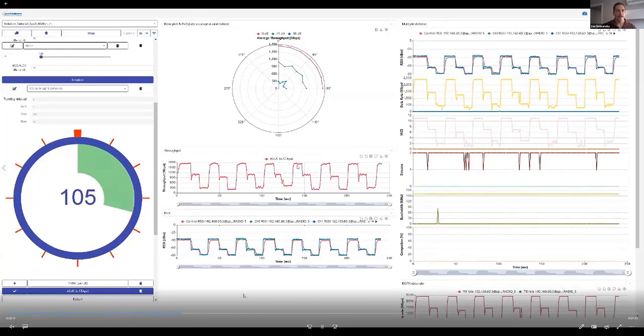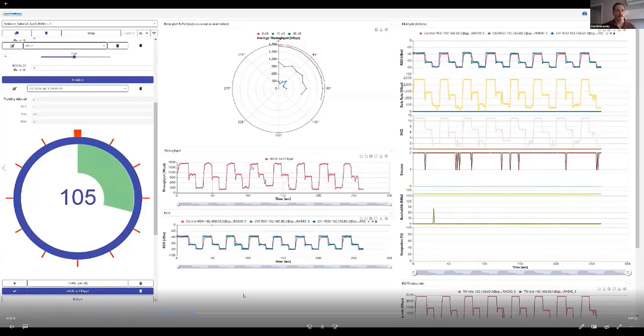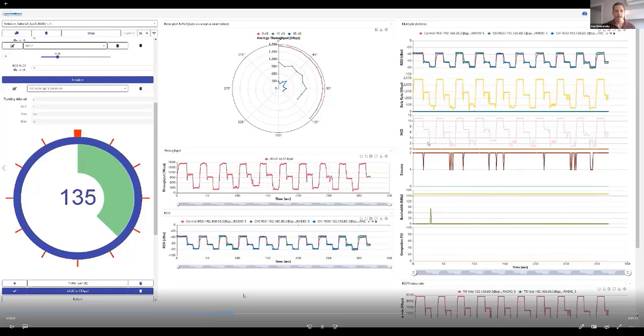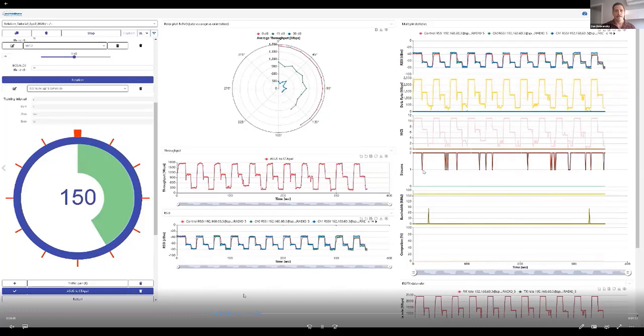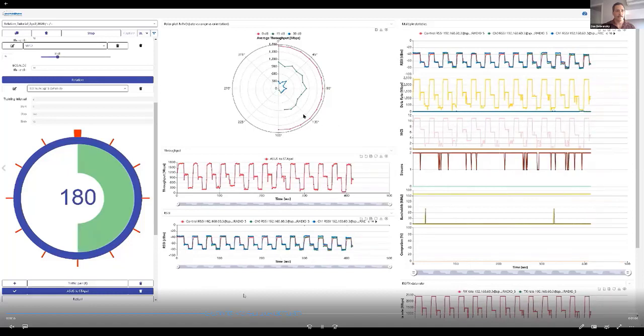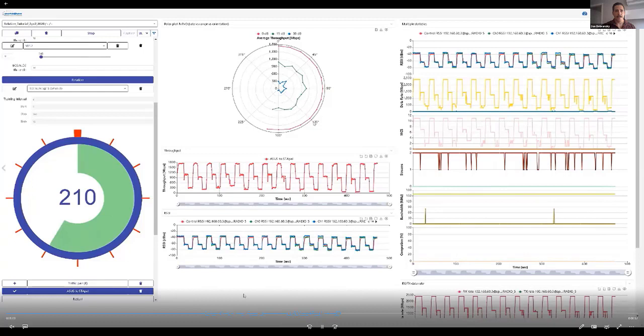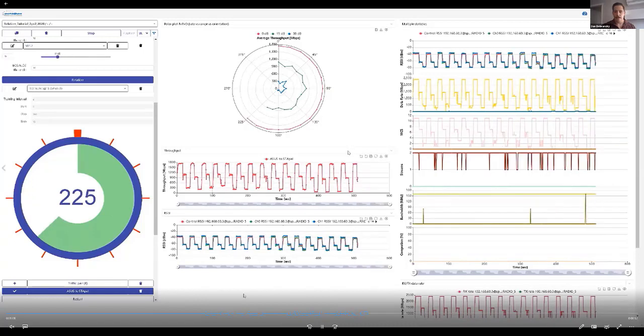And this is really critical if you want to stress the chipset and make sure that it recovers to those 11AX data rates, MCS levels, and even streams. So you can make sure that you're trying to have as much bandwidth as possible in the highest MCS levels throughout the whole test. But yeah, I guess this is the third and final rotation-based measurement. So I will throw this back to Lee to close things out.